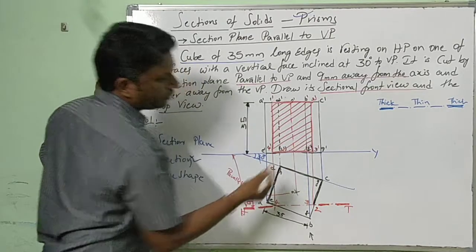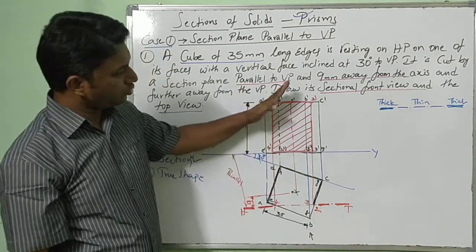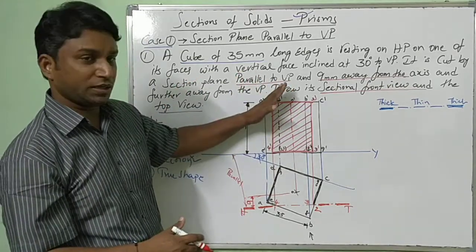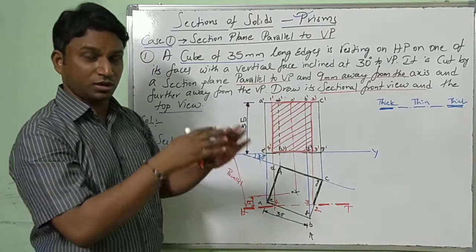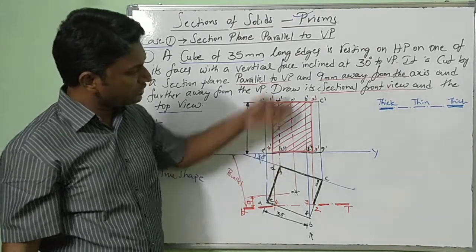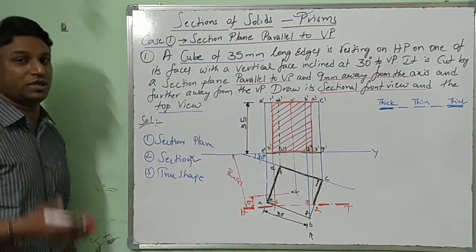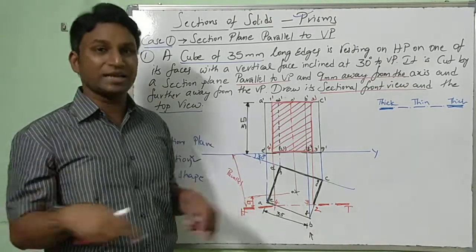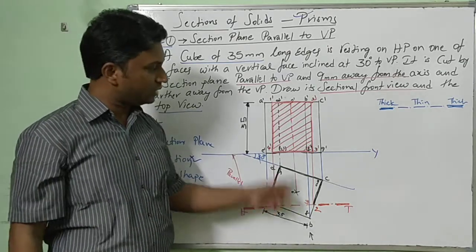Inclined. This is a rectangle box. I have to draw inclined lines, maybe 30 degrees or 45 degrees. You can fix your drafter, keep that, right? And at regular intervals, not less distance, large distance, you have to do hatching. You have to draw parallel lines. That's called hatching: drawing parallel lines at regular intervals inside the box, which is newly formed from the sectional plane.